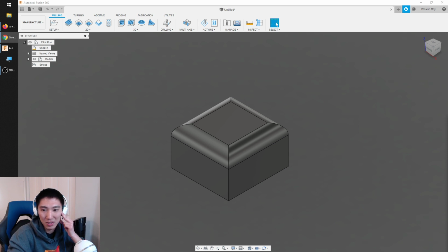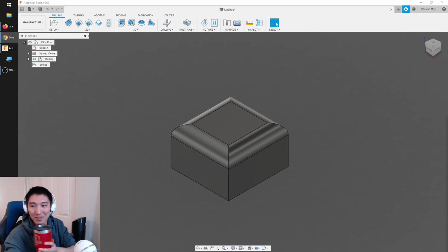What do I use the most, Shapeoko or Nomad? I personally use the Shapeoko more, just because my projects tend to be larger, and I like the material removal rate of the router, which is 1.25 horsepower versus the sub 100-watt spindle on the Nomad. So I can plow through aluminum a lot faster, and my requirements for accuracy aren't nearly as stringent. So I usually just say, screw it, I'm going to do it on the Shapeoko. It's faster, and it's bigger, so I can clamp things all over the place and not worry about running out of work area.